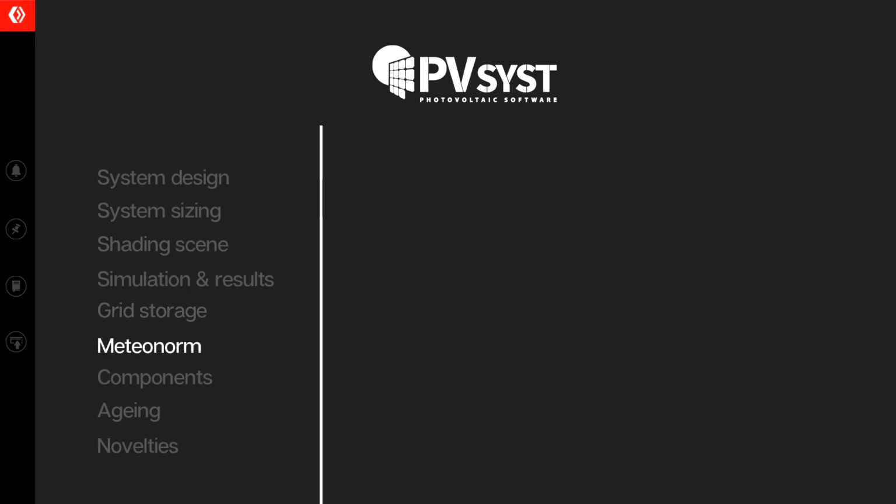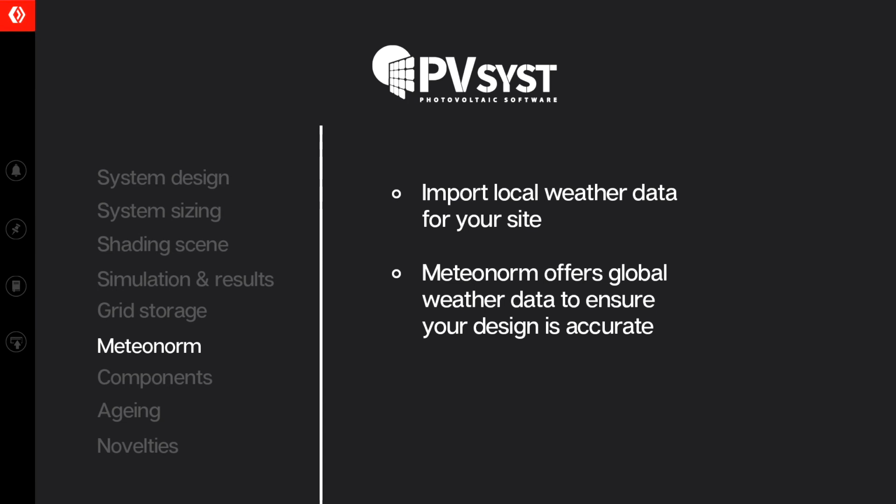Basically, the solar generation that we get from any site is dependent on the weather or the climate data out there. PVSyst provides us a feature wherein we can import the weather data right from Meteonorm and include it in our simulation. Meteonorm is a third-party software that has a large database of various weather sites from across the world, and it is very convenient for us to locate the weather data for the location of our project.